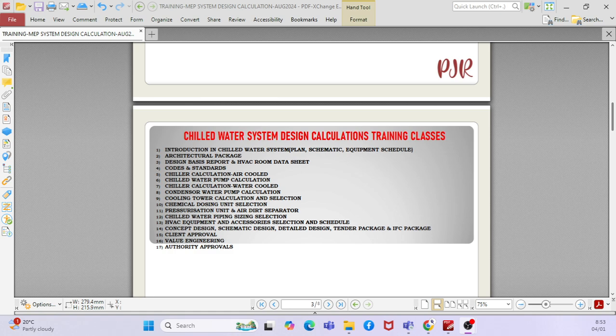Actually, for example, shall I share a small experience? Sure. Last time I was calculating the water supply flow rate, so I was taking a reference for the WSFU value. I checked the Abu Dhabi code, and I have one more code with me, the British Standard, BS standard. When I checked both, as per the WSFU in the Abu Dhabi code the flow rate is very high, but when I take the BS standard, the flow rate is less. So I am really confused.